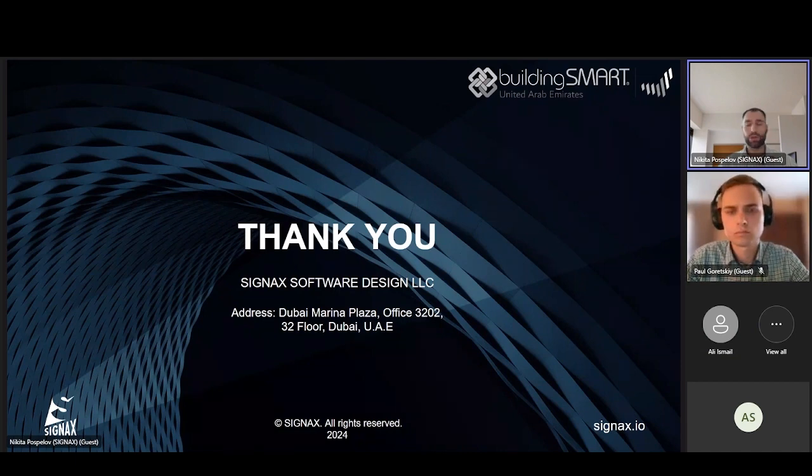Yes, you're right. Not every contractor has the skills and ability to use BIM right now, but on this specific project, four out of five subcontractors and designers were able to use BIM technology, and it was not a problem. But for a couple of the subcontractors, we had to train their personnel, for example, how to export the IFC format, how to set up the export, and how to create federated models, so they were able to process clash detection and model coordination themselves.